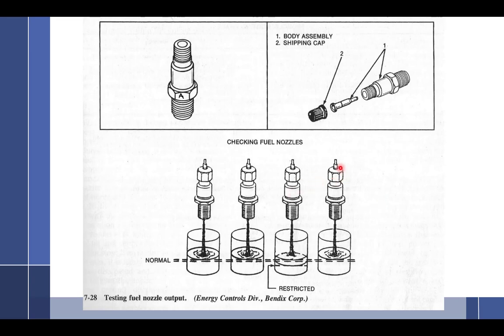So if you talk to somebody, and so Sacramento Sky Ranch are no longer around. They used to make all the hoses for us. So I'd go in and get a nice, this is how it's done in a shop. I'm like, wow. When they build hoses, it's a lot different than it's done in the field. First of all, they build the hose, nicer equipment, and then they sight through it. They use brushes like gun cleaning brushes, go through it a bunch of times. Then they put it in a case that has safety on it, and they pressurize it to 1.5 times its burst pressure. And then they flow test it both ways, and so it's a lot different. Anyway, that's my soapbox and why you'll never see me making a hose.